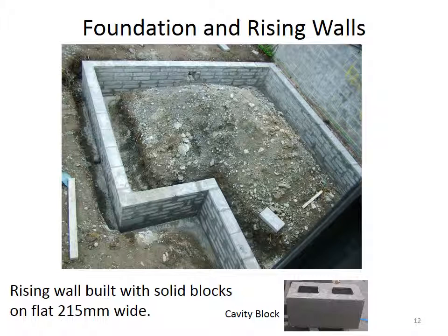The rising walls are always built up using solid blocks, not cavity blocks, which is the image in the bottom right hand corner there. It's a cavity block. We never use them for our rising walls. They have to be solid walls.